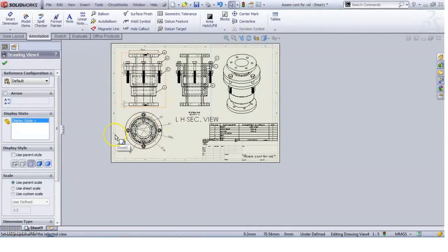The rest of the procedure is the same in all; just some commands will be here and there. You have to create the 2D sketch, then create separate 3D parts, then assemble all the 3D parts, and then you can create a drawing sheet. This is all you have to understand while using SolidWorks modeling and drafting.